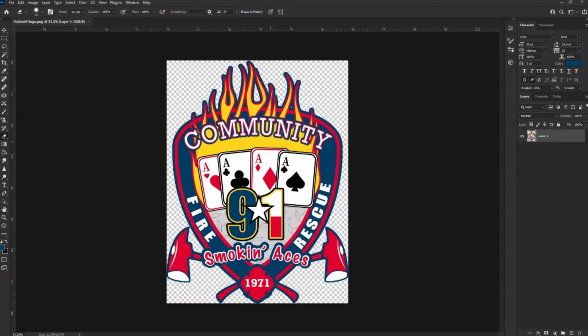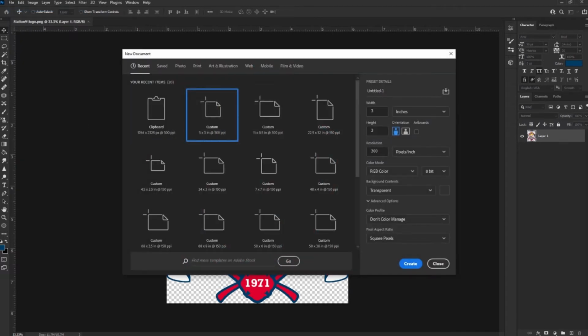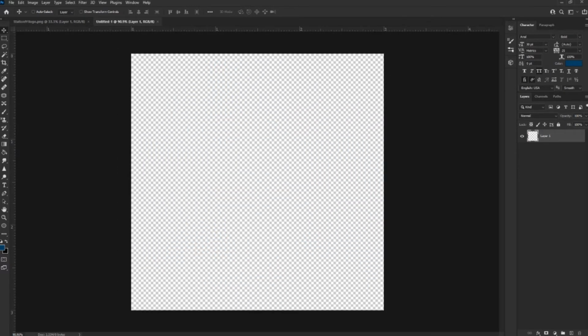All right, back to this. Now let's assume that you already have your cutout and this is what you want it to be cut out as. You have your PNG set up. What you're going to do is you should know your rough dimensions of about what you want it to be cut out as. I want mine to be about 2 inches final. So I'm going to set it up as a 3x3 so I have a little bit of wiggle room, and you'll see why we're doing that. I have a 3x3 image. You choose what you want, but it is important that you choose the dimensions and keep it that way. You can't choose something then try to go back in and crop it and change it, because it's going to have to be the same for Illustrator. So make sure that's a critical step. Choose it and stick with it, or you're going to have to start over.